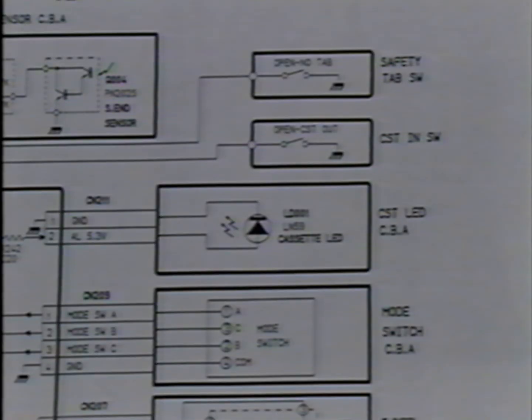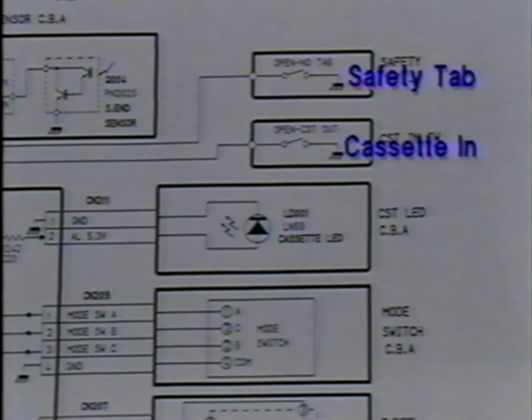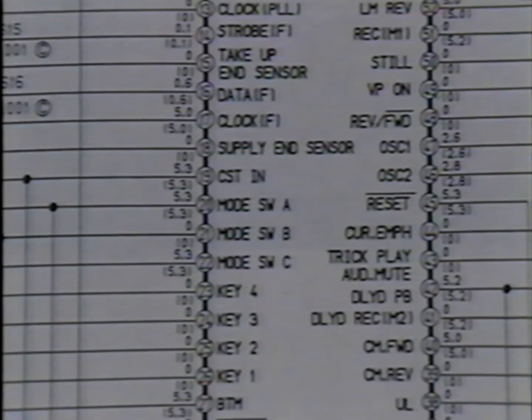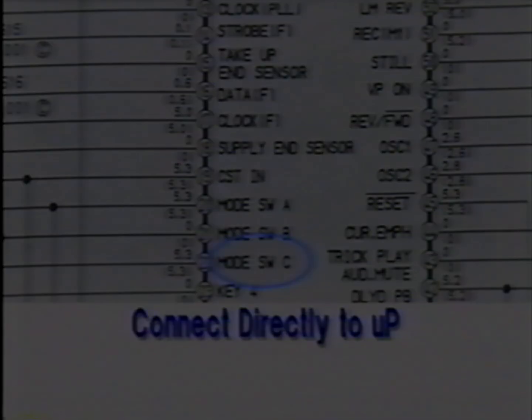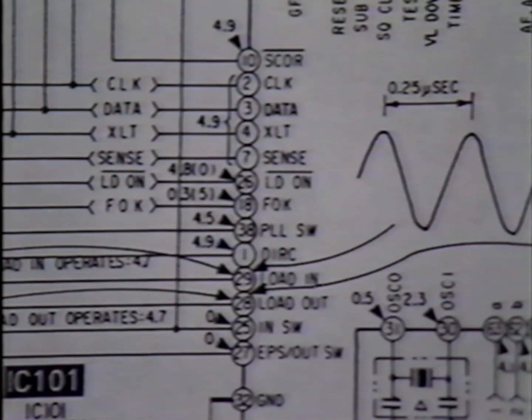There are typically several switch or sensor inputs in a product that monitor go, no-go conditions and are directly connected to the microprocessor's input port lines. When considering the trouble symptoms of a product, do not overlook these simple input devices and the easy tests for their proper operation. In most products, this kind of single-bit go, no-go status information is also provided to the microprocessor by other ICs in the system. These inputs can also be crucial to normal operation of the system.